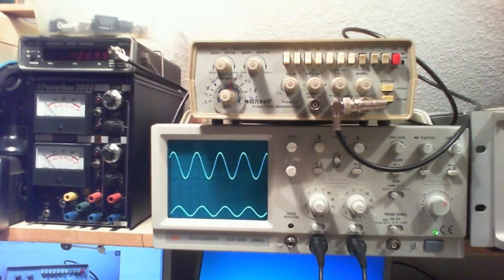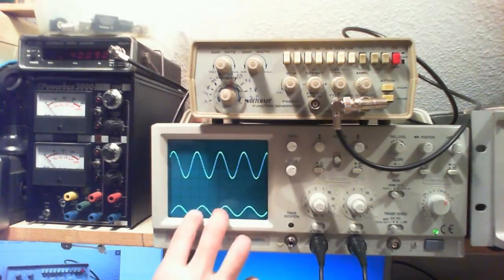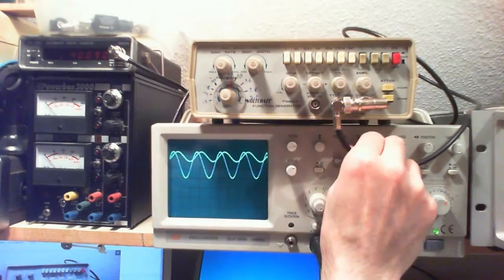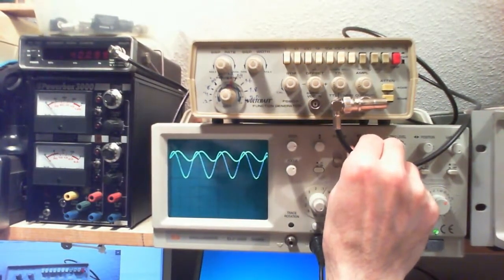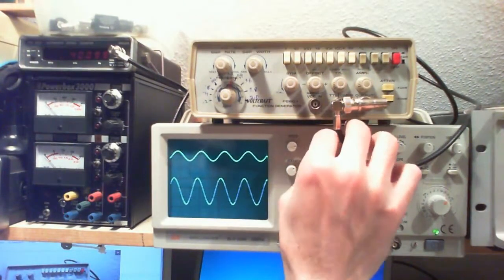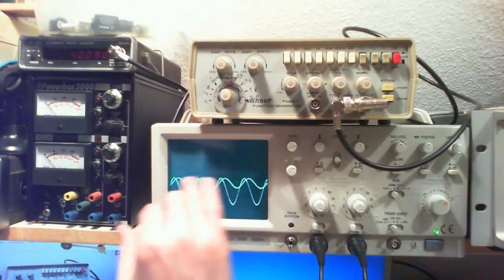So that means that 1.2 horizontal units corresponds to 180 degrees. So now you can read the phase difference between the two signals, meaning that I can move this up here, and you can move both of them down here to be able to read something that makes sense on this line over here.